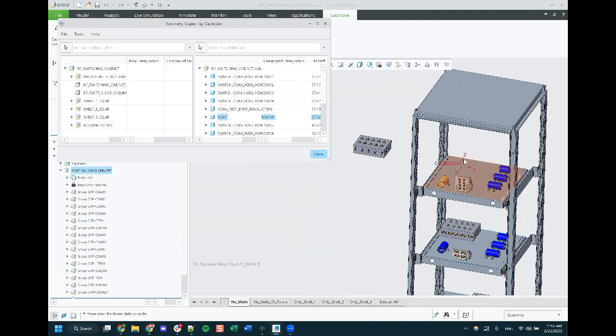If I select, we can see there's the component placement coordinate system. This is why all of those copy geometries are located in this spot. It's also the difference between assembly context and external copy geometries, the fact that you need this coordinate system. Side note, also the reason that external copy geometries are more lightweight than assembly context copy geometries.